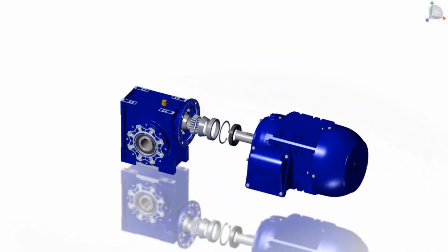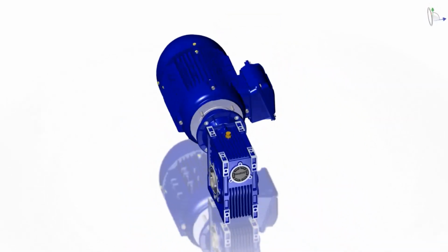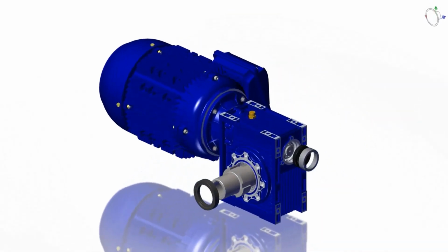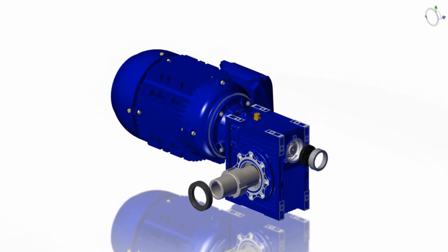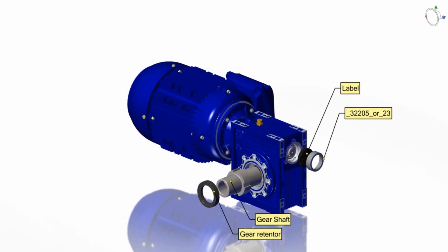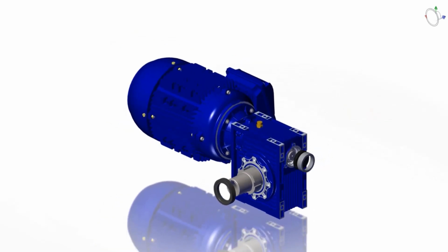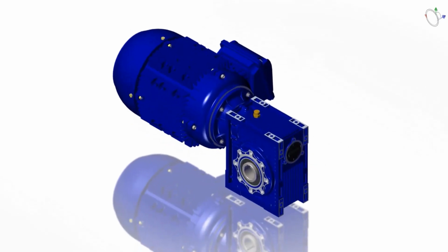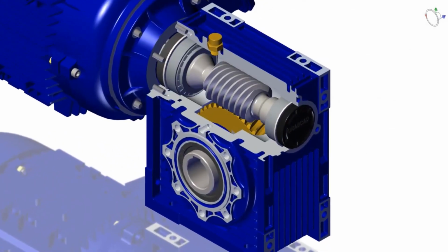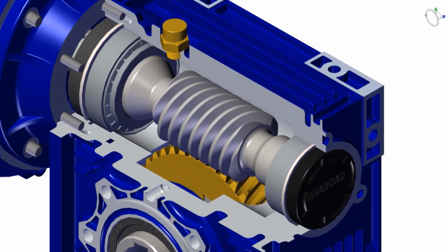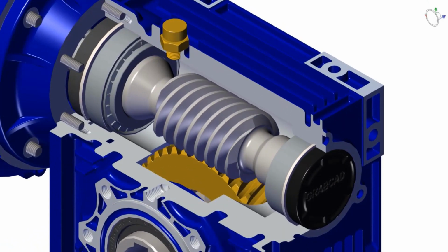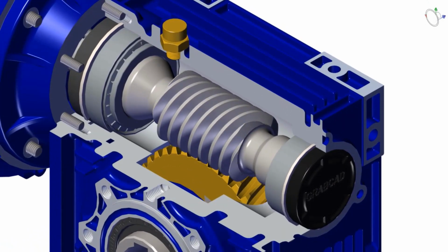So animation can be created extremely quickly by utilizing the 2D views created in your project. This can be done by dragging a view into your animation timeline. The timeline will automatically create the required keys for the animation of your product. As you can see, you can also utilize configurations and give movements to your product to show the exact operation to your customers, or internally in your production department or manufacturing department as well.